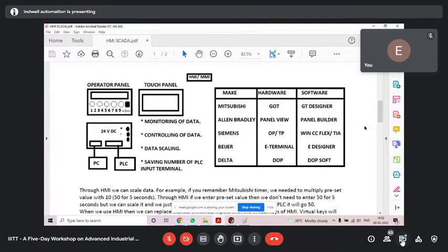The requirement is in the HMI software. Listen, in the HMI software, you must have that PLC option. When you open the HMI software, it will ask you which PLC you are going to interface, and it will give you default names. Some brand names will be given. So if your PLC name is in that list, you can interface that PLC with that HMI.